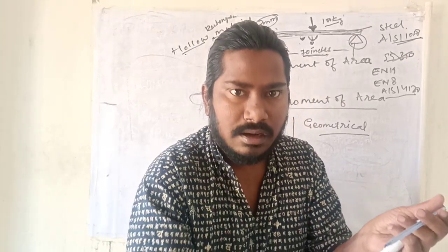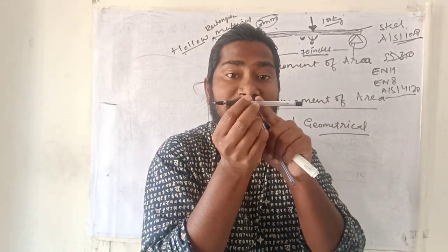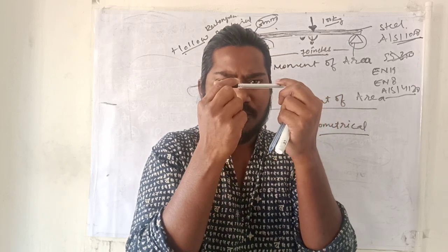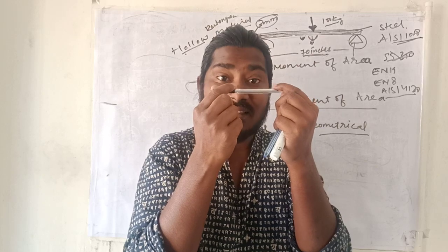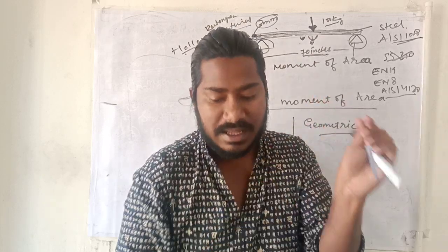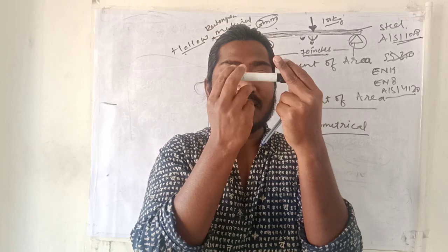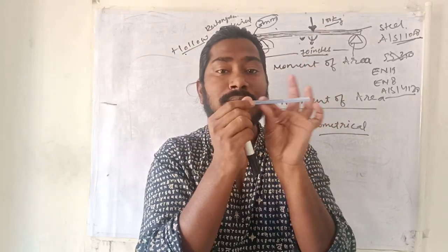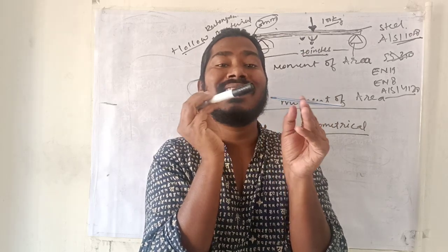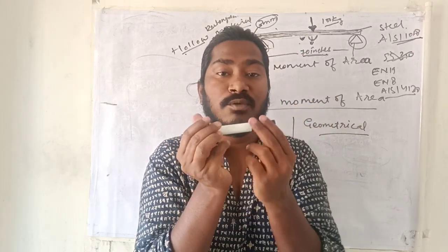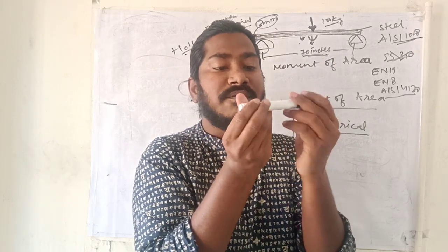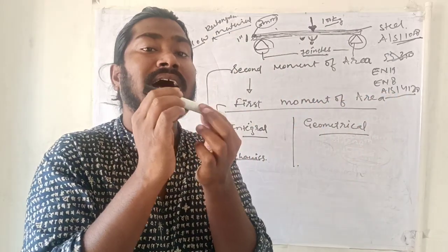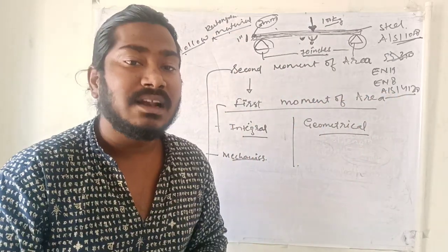Now the second pen, its weight is absolutely the same as this pen. If I try to apply the load, the flex in this pen would be lesser in comparison to the flex in this pen. Or I would say the flex in this marker would be lesser than the flex in this pen if the weight of both is absolutely the same, or the material of both would be absolutely the same, because here you can witness this pipe or this marker has a higher cross-sectional area.